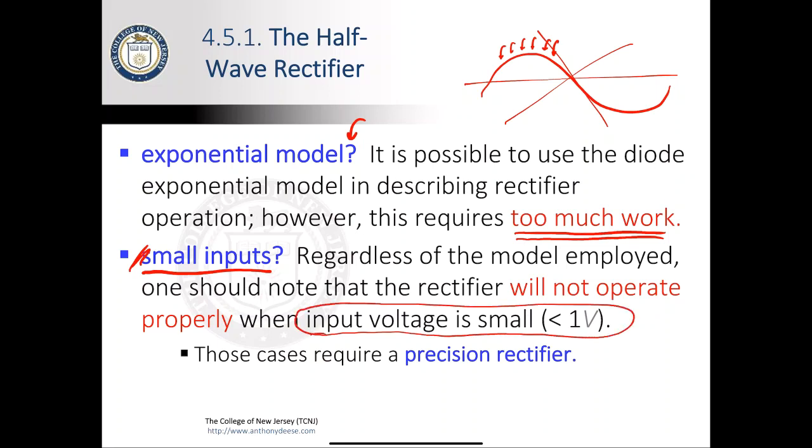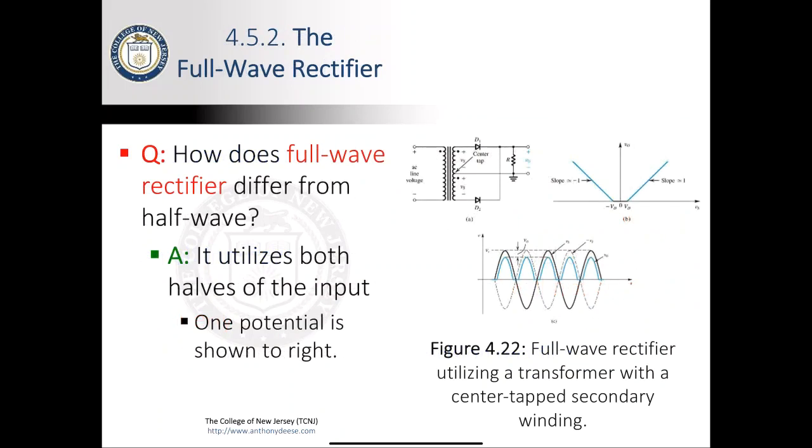We're not going to talk too much about how a rectifier is used or how it reacts for very small inputs. It's not really a popular application. If you want to do it properly, you have to use something called a precision rectifier, but again, that's not necessarily a topic that we're going to spend a lot of time on. For our purposes, we are going to be assuming that our Vs is going to be greater than, let's say, 5 volts or so when we are talking about any problem related to rectifiers.